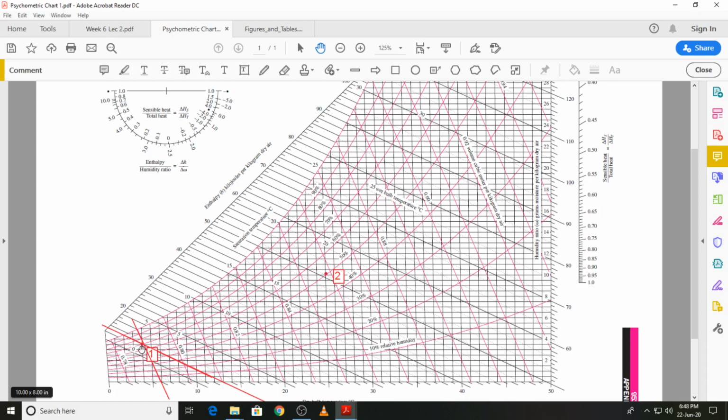So we are just below 0.79, approximately 0.789 meter cube per kilogram dry air is the specific volume. This is 0.78, you can see over here, and the line that we are interested in is the line over here, so it will be around 0.789.